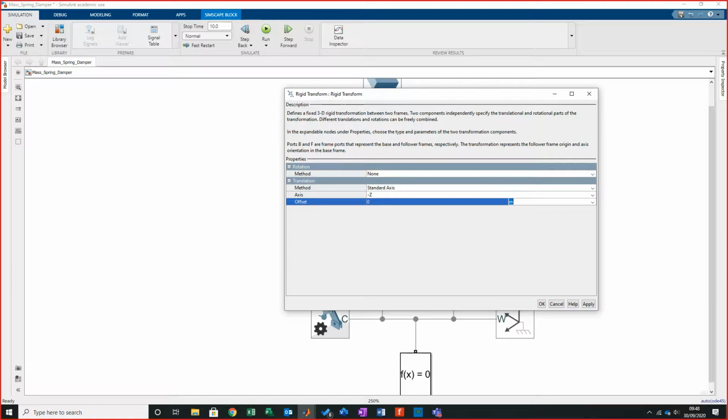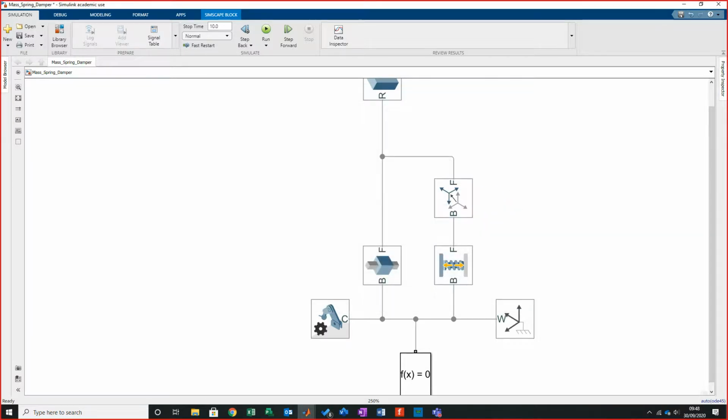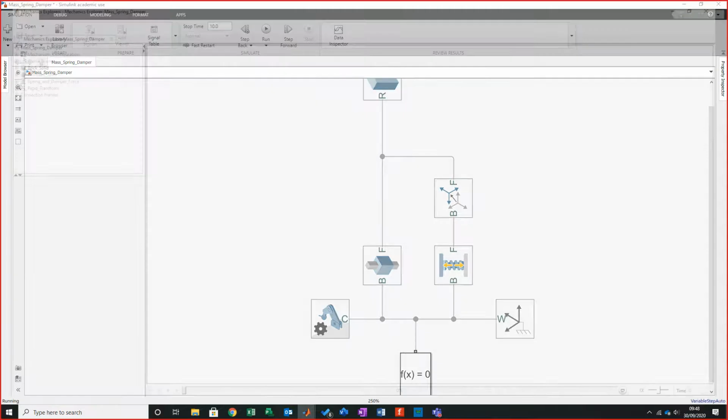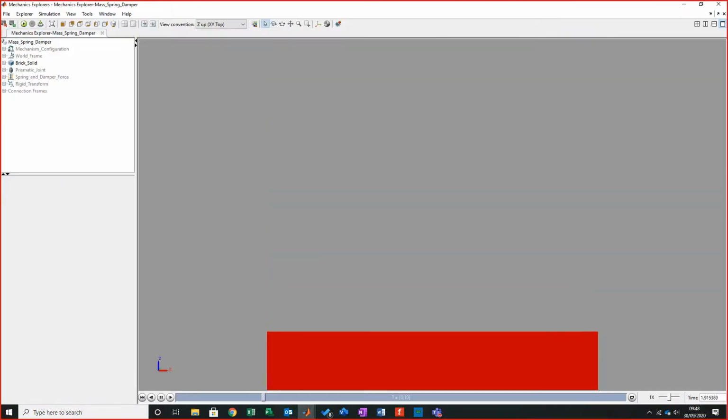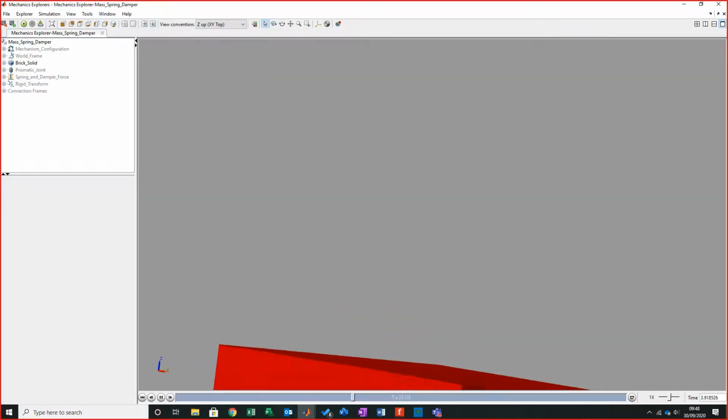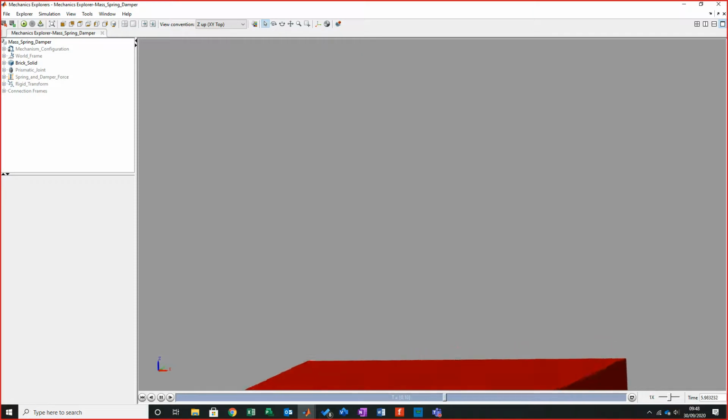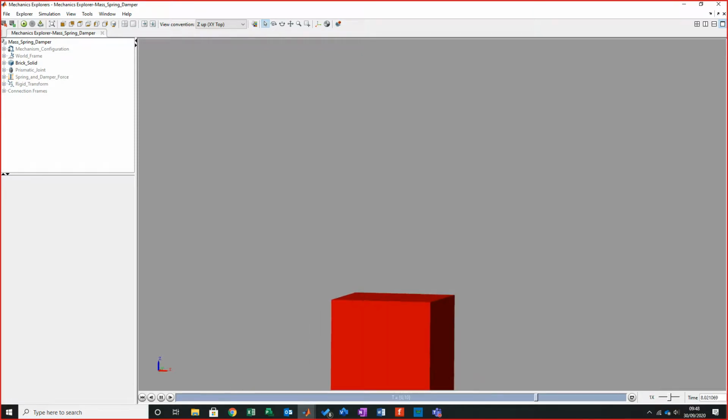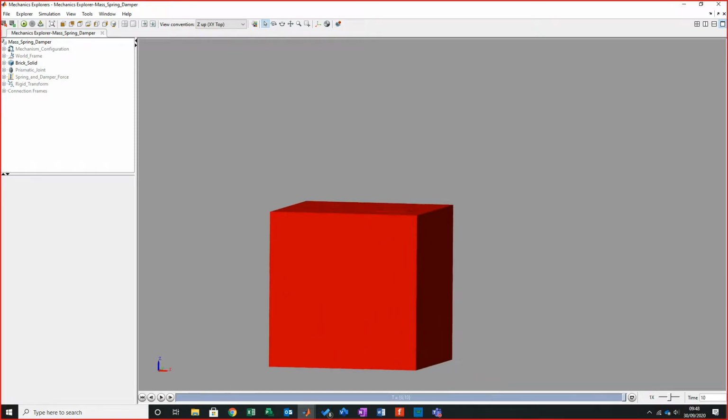Make sure you change your units, by the way, to millimeters. If you remember, we did 50 by 50 by 50. We're coming from the center, so as ever, 50 over 2 will go 25 millimeters. Click apply, and all that will do is shift it 25 millimeters. So let's run it again. Whoa! That is more like what we were looking for, ladies and gents. We were looking for a much better approach.